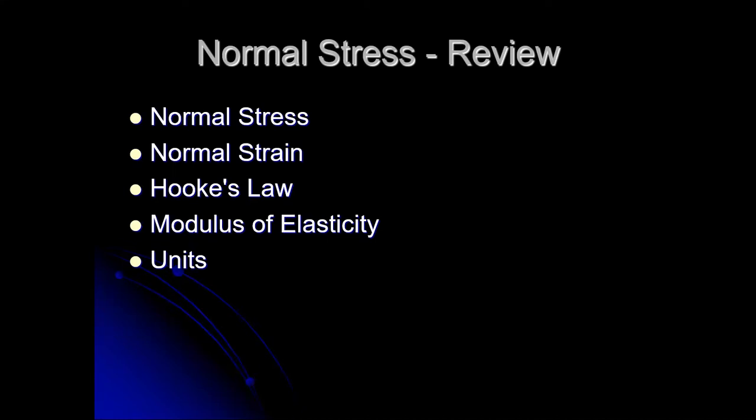We have to be careful on the other side of that, though, when we're generating stress or we're generating strain by taking force over area or length, elongation over length. There, the units have to be consistent. So areas, for example, always square inches for our purposes. Otherwise, we won't get PSI or KSI.